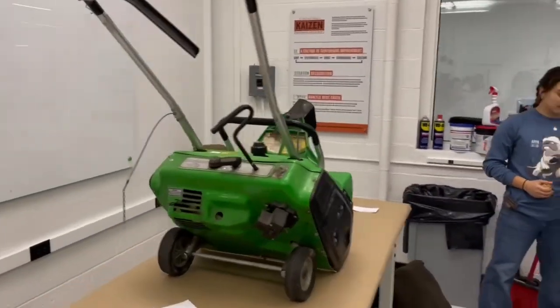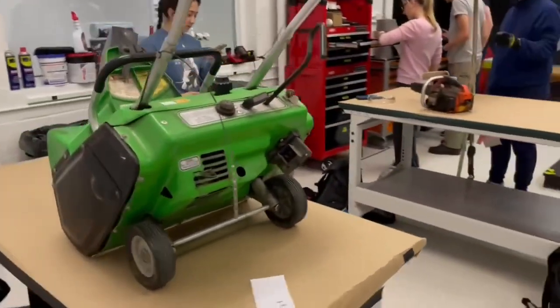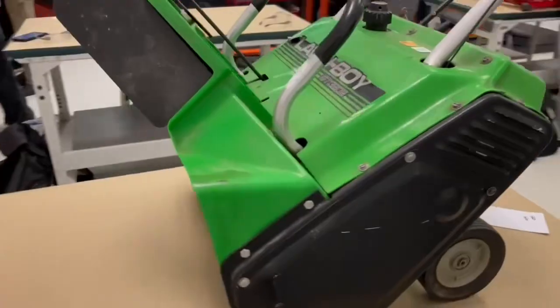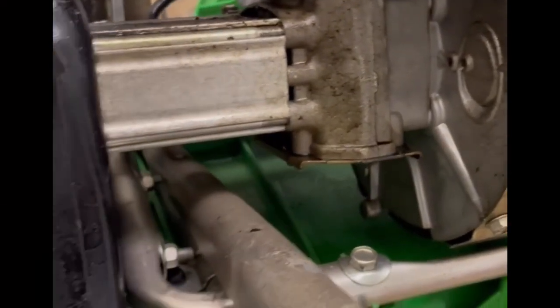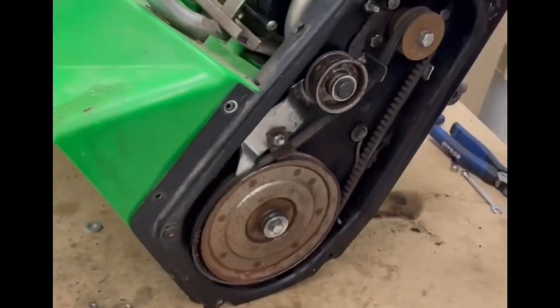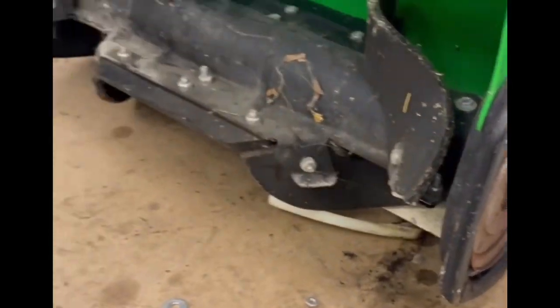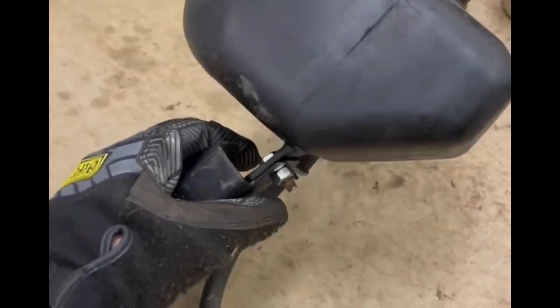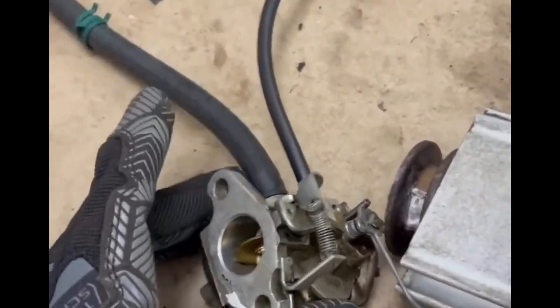Have you ever needed to shovel snow from your driveway? Not as SoCal residents. In a funny twist of fate, we got the opportunity to investigate how a snowblower works for our FMD project. Our snowblower makes y'all's life easier by using a two-stroke engine to drive a belt that then rotates a set of rubber blades located on the bottom of the snowblower. Those rubber blades then redirect the snow upwards and ultimately to the side.